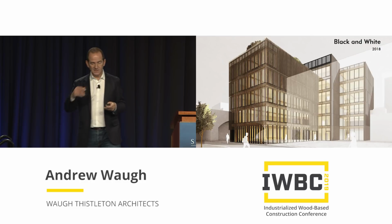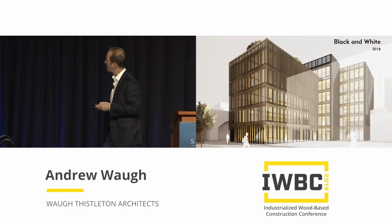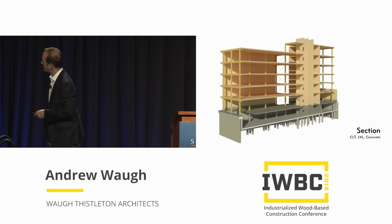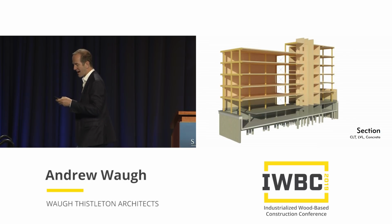And this building, again, we start on site here at the beginning of December. This is about 40,000 square feet, a 6-story office building. And this one is built entirely from timber from the ground floor up. So this is hardwood beam and post and softwood CLT slabs and softwood CLT core. And this will be start to finish in about a year.